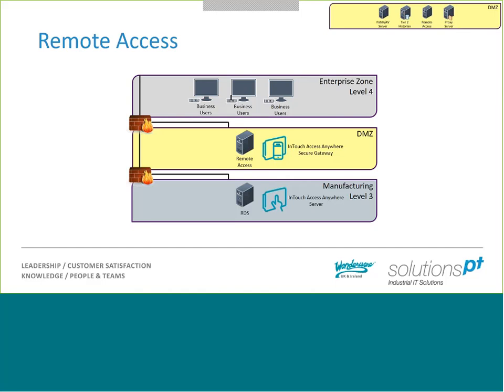An authentication server is installed on the same computer as the secure gateway, and this authentication server authenticates InTouch Access Anywhere users before granting them access to the InTouch applications, and that's the important part of it. And for those of you that don't really know what InTouch Access Anywhere is, it's that web front end so that you can display a complete InTouch application in a mobile form.